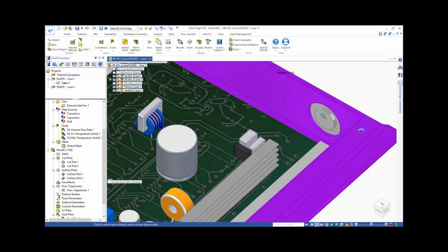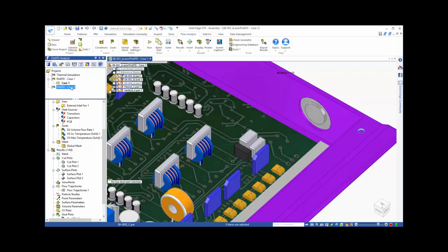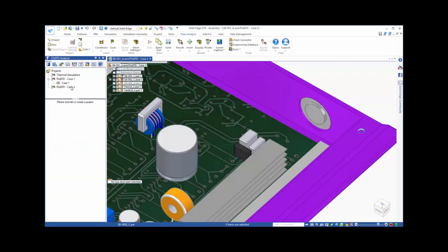One of the ideas that we would like to test based on our first solution is to shift the fan slightly towards the center of the amp. We are hoping to divert a portion of the incoming airflow more towards the central region of the board to cool those components better, while still maintaining strong flow through the heatsink. Additionally, we will go ahead and increase the length of the heatsink fins to further help cool the transistors. So we have set up a second family of assemblies member in Solid Edge that reflects these design changes.